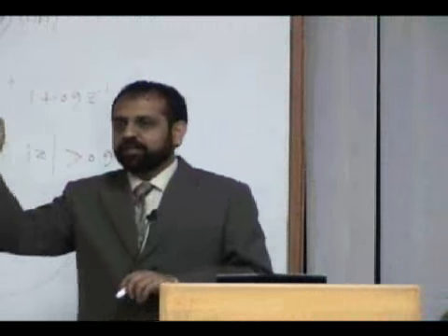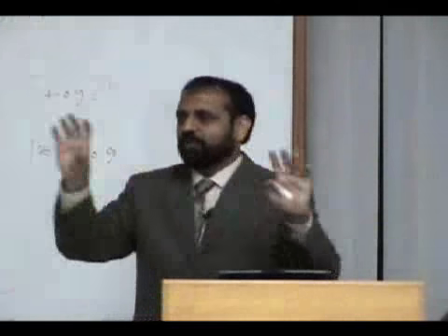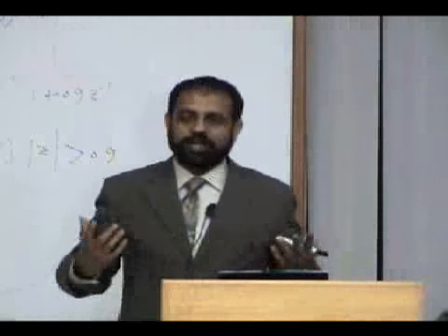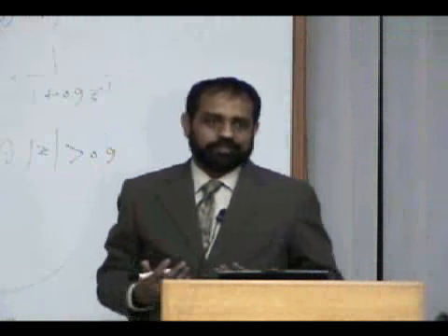So in MATLAB, looking at the difference equation, you can ask MATLAB to plot the poles and zeros. MATLAB will plot all the poles. See whether all the poles are inside the unit circle or not. If they are, you say the system is stable. If not, then the system is not stable.